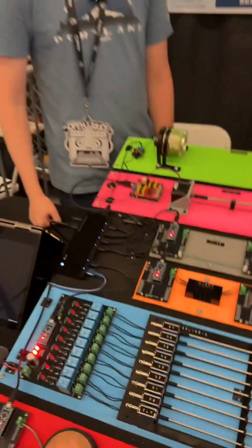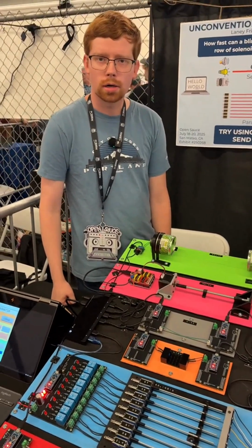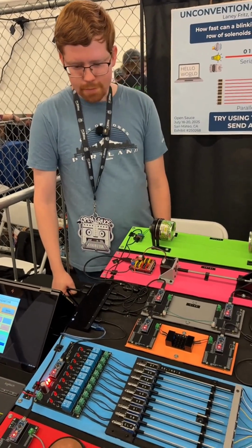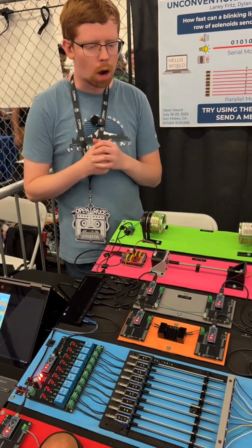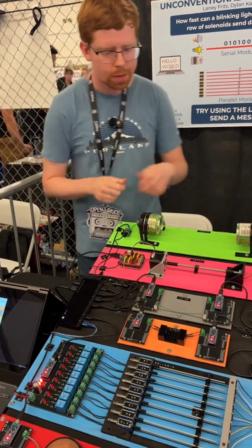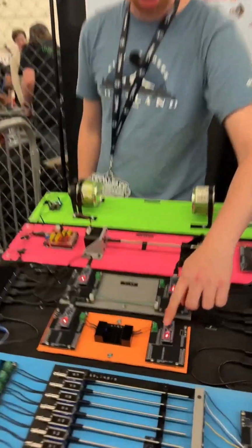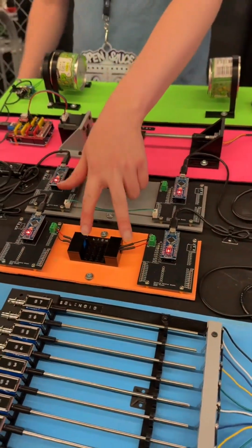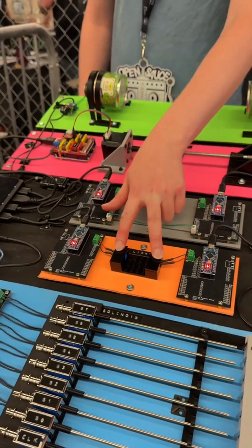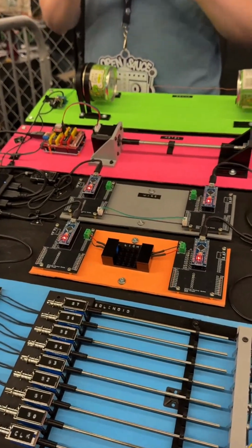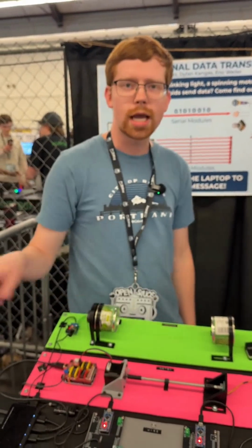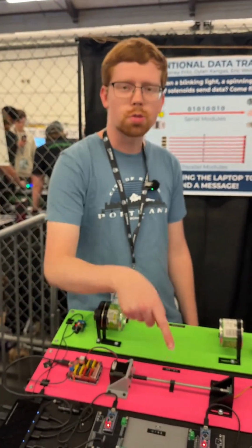Very cool. And of all these, what was the hardest, most challenging to build, that gave you the most trouble? I don't think any one module in particular was the hardest. The hardest would have been the code for the receiver on the light and the touch, because these don't actually have that clock. So we have to do some special, it's called differential Manchester encoding, so we can actually send the data without a clock. That was really hard to program.